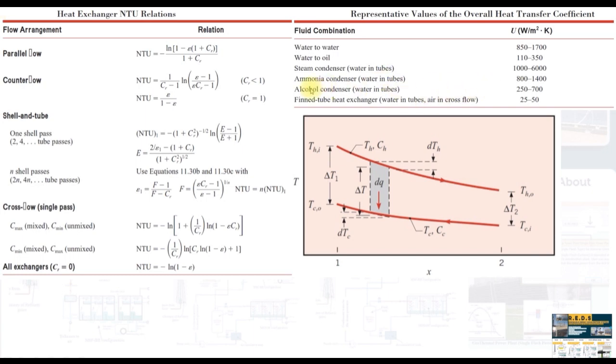You can use ammonia, toluene. It's up to the user, because this model that we are going to talk about is simple, not complicated. There is no use for integrators or transfer functions or something like this. A user can add more working fluids, can add more types of heat exchanger, and can transfer this model into a dynamic model by signal generator. You can put inside the block of signal generator the overall heat transfer coefficient, inlet hot temperature stream, inlet cold stream, and so on.